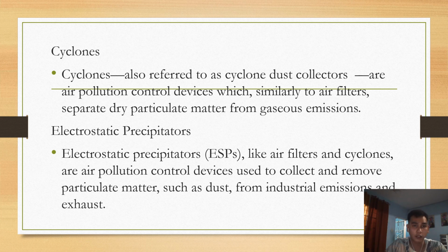Similarly to air filters, PM accumulation is periodically removed from the collecting plates and deposited in a collection hopper below, either through mechanically dislodging the particulates or by introducing water to clean off the particulates. Electrostatic precipitators which employ the latter method are known as wet electrostatic precipitators. As electrostatic precipitators typically have multiple collection plates, their efficiency often exceeds 99%.